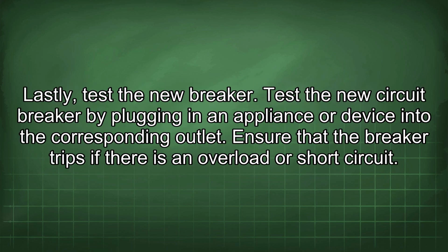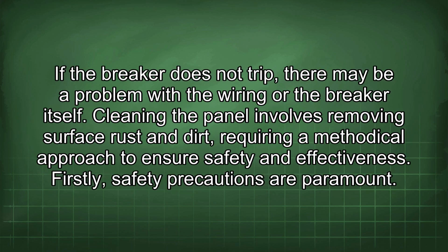Lastly, test the new breaker. Test the new circuit breaker by plugging an appliance or device into the corresponding outlet. Ensure that the breaker trips if there is an overload or short circuit. If the breaker does not trip, there may be a problem with the wiring or the breaker itself.